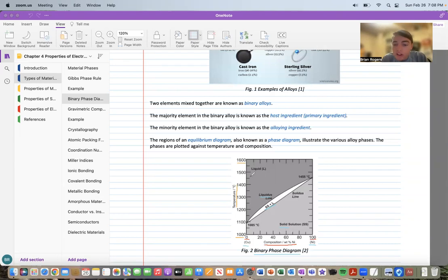And so you'll notice for the binary alloy, if we do 50% of copper and 50% of nickel, that would refer to this middle tick right here. But if we do 40% of copper and 60% of nickel, we locate 60% of nickel, because the x-axis represents the percentage of nickel. And then the remaining 40% must be the other element, which is copper.